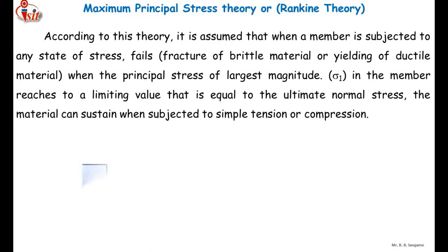So first of all, let us take a component. Here I have considered a component on which I am going to apply a stress in the x direction, which is sigma x. It is the normal stress; you can see that it is acting perpendicular to the area. Next is sigma y, the normal stress acting along the y direction, and the same component is subjected to shear stress, that is tau xy and tau yx.